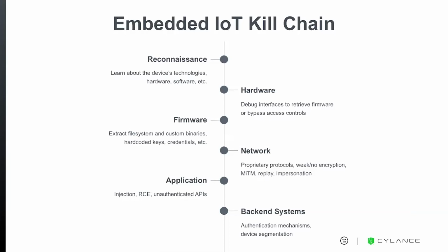And you can, again, as I was saying earlier, emulate that firmware to perform dynamic analysis against it. Couple that with static analysis of the binaries, so disassembling them and looking for vulnerabilities in them. And giving you some ideas, what we look for there is things like bash injection, especially through CGI functionality on embedded web servers, which you don't really see in enterprise environments anymore, but has made a big comeback, so to speak, in embedded systems.